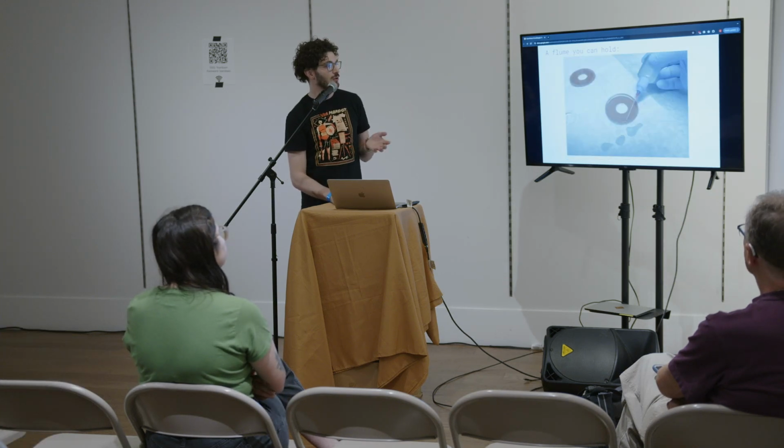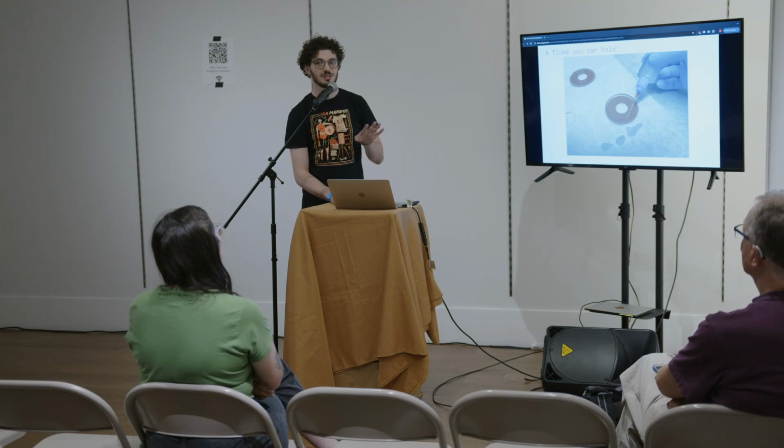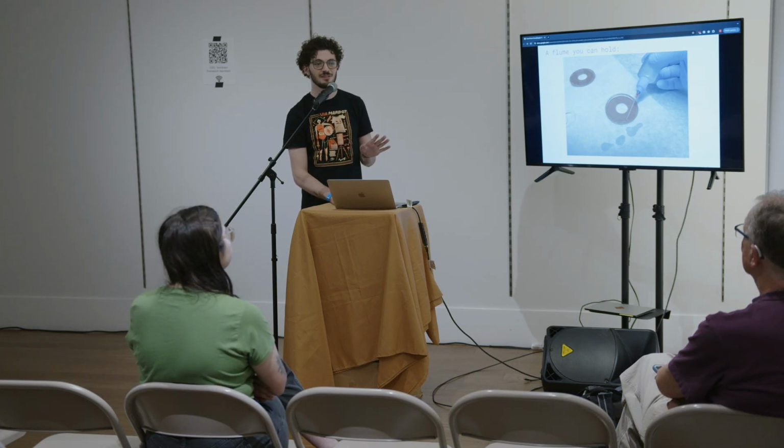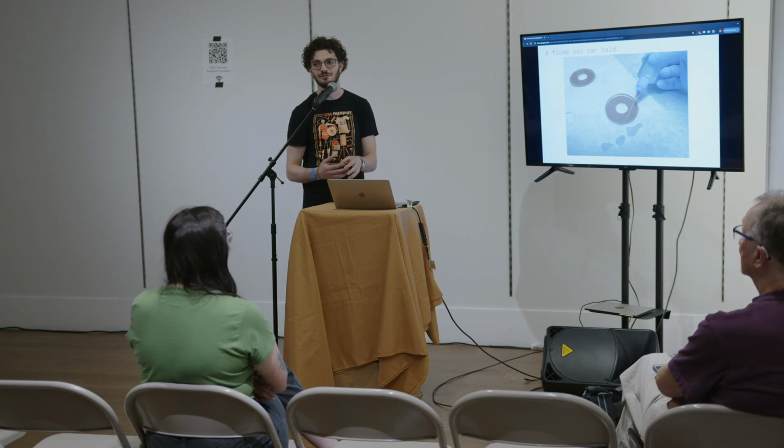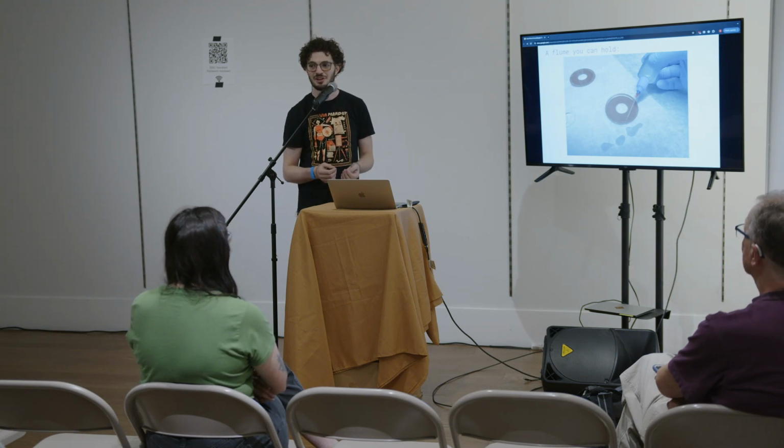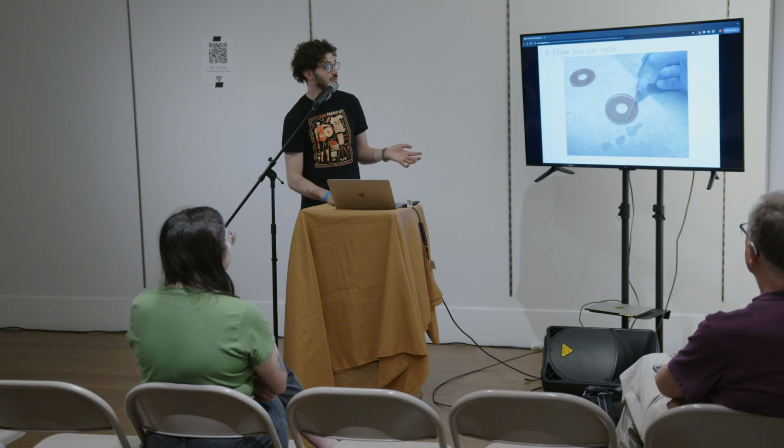So one big tip when you're doing anything with acrylic is you want to leave the paper on as long as possible. Any surface that you're not going to need to glue right now, leave the paper on, because especially with the solvents, you'll get defects on the surface from little drips getting everywhere. Like some solvent on your glove, you'll end up leaving a fingerprint. So that's one big tip.